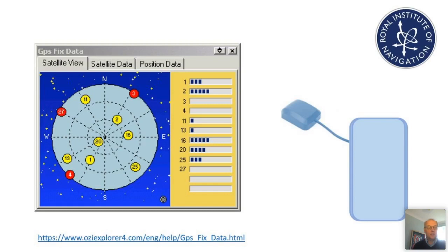If you count them up, I think there are 10 satellites visible there. 3 of them are in red because they're very low elevation. This sky plot has the 0 elevation around the edge, going up to zenith in the center. So really, you've got 7 satellites available to you, and that's fairly typical from each constellation.